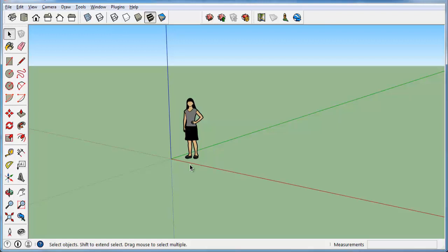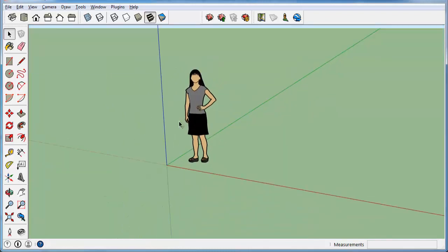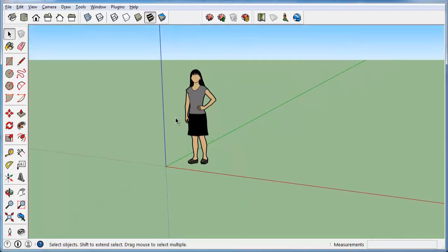Then also notice here, and I bring this up because most people, when they get going with SketchUp, choose the first template that is presented to them. Template being how SketchUp is presenting the geometry. Notice here that it's a little bit artistic. You have fat lines and you have thin lines. Be aware that you can actually change this to make it look as sharp as you need when you're designing. And being in the construction space, you may not be interested in an artistic look, but more of just a really sharp visualization of your models. So if you happen to be in some kind of mode where it's showing a lot of thicker lines and thinner lines and perhaps some things that look very artistic, be aware you can change that.